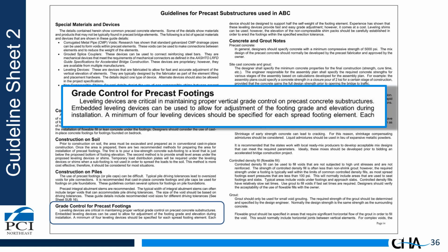Grade control is very important. We do recommend the use of grade adjustment devices, either cast-in leveling devices or shims, to make sure that we hit the grades that we specify.